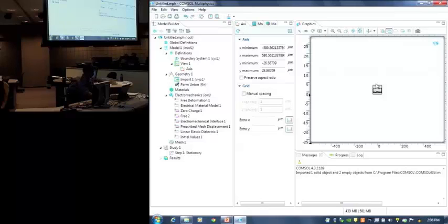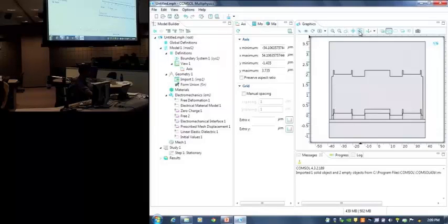Now, to be able to get the geometry as a whole in this GUI or this graphics window, you can click on this Zoom Extents button, which shows up as a toolbar on top of this graphics window. So now you're seeing a compressed shape of this geometry so you can clearly see what are the boundaries within this geometry. I'll tell you more about the electromechanical device as we model, so you'll know what are the materials within here. It's basically a resonator, and there's a dielectric, and there's a substrate, and then you have air around it.